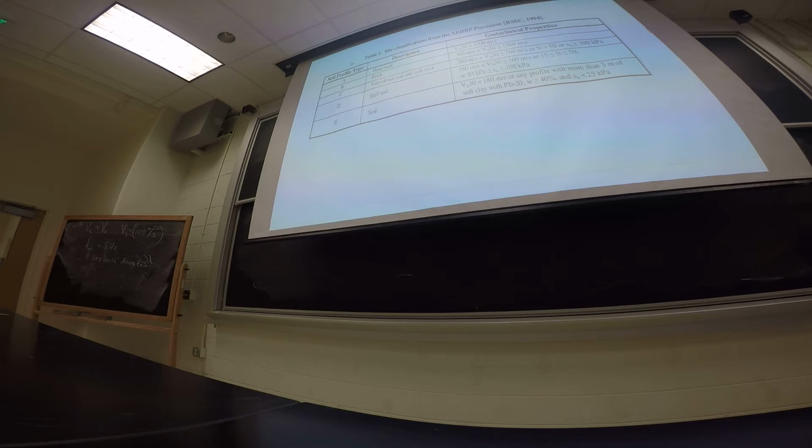So if I can measure shear wave velocity through Rayleigh waves at different frequencies, I can get an idea of the lithology, or at least the stiffness of the rock, whether it's soil or rock, as a function of depth. And this could be a lot cheaper than taking a core or drilling a hole. Okay, so this is actually a comparison of actual versus predicted using surface wave data. And you can see that the errors in this case were just a few percent. They actually weren't that significant.